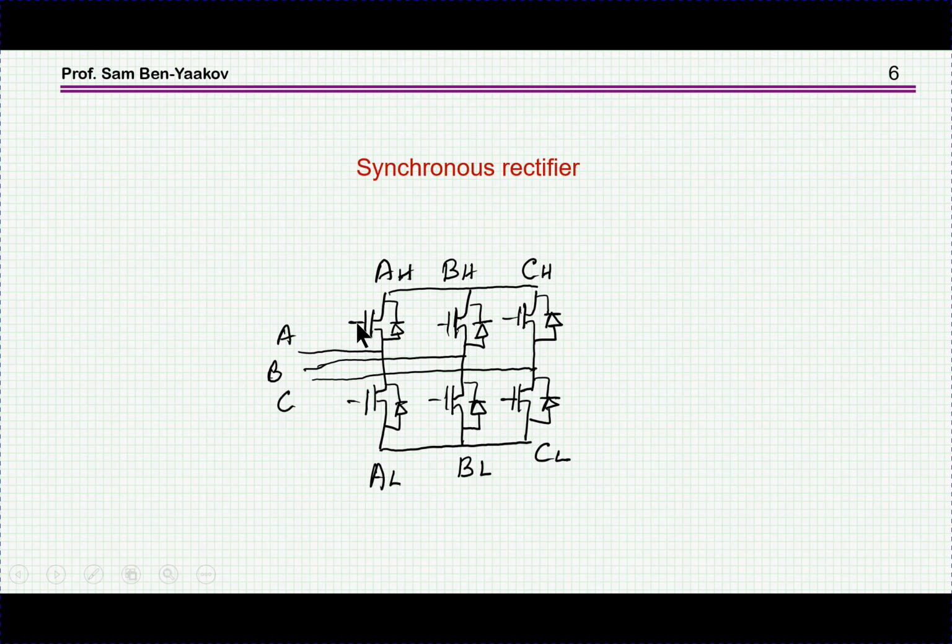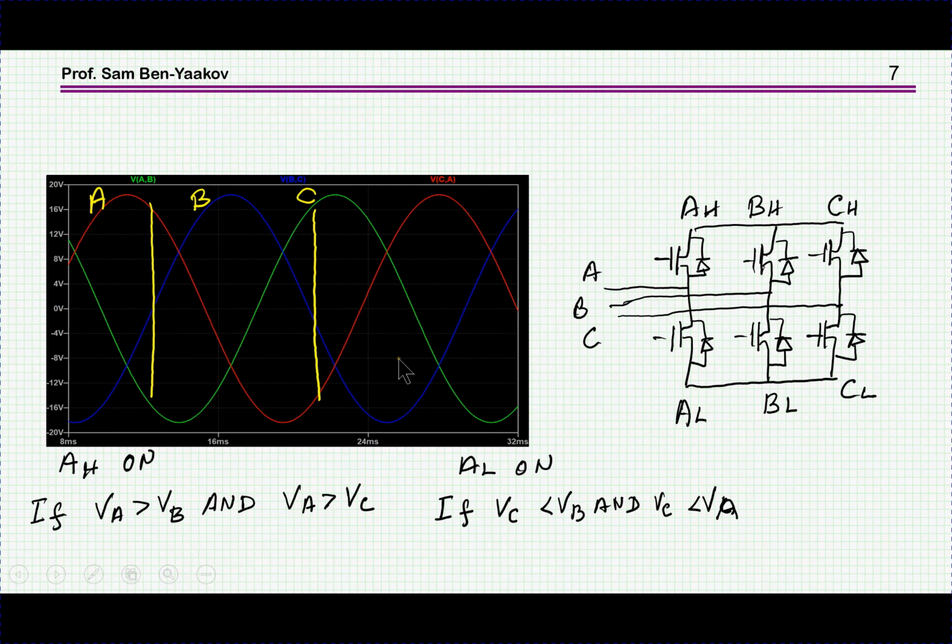So here are decisions to make: when to turn on these transistors. I'm not talking about PWM, or a buck converter or boost converter. I'm just talking about a regular rectifier where we want to lower the losses by having transistors in parallel to the diode, and therefore the voltage drop will depend on the RDS(on) of the transistor, and if it's a few milliohms, then we are in good shape. So this is a logic decision that we can express as a Boolean expression,